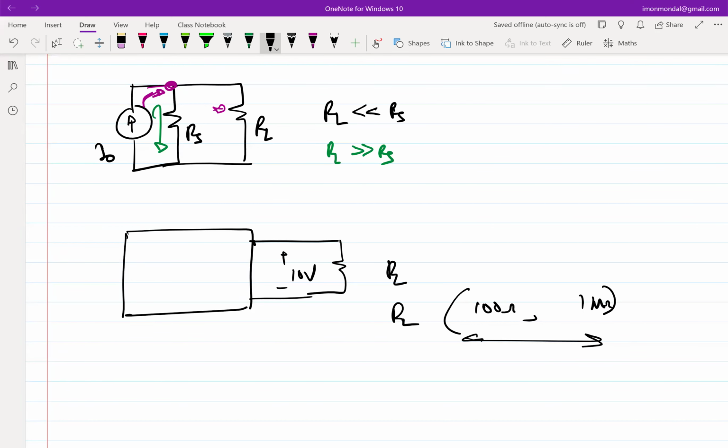So what is the first step back? The first step back is to understand what should be the internal resistance of the voltage source that I am trying to build. So the specification for the internal resistance of the voltage source should be much, much lesser than RL. In this case, minimum RL, which is 100 ohm, right? Much lesser than 100 ohm. Make sense? Extremely important concept. If it doesn't make sense, I will repeat. Very simple concept, but extremely important. Does it make sense? Okay.